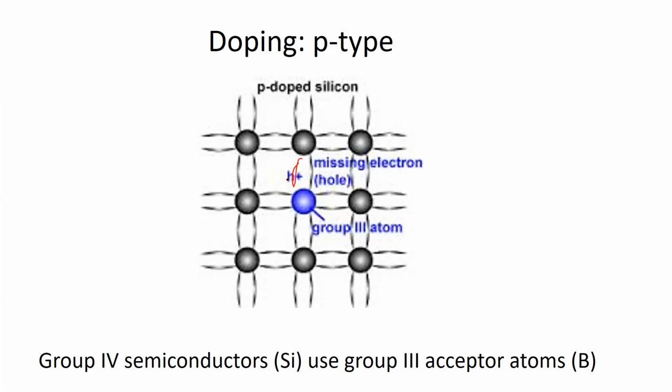They've got this extra electron, and so the boron atom becomes a negative ion. And these negative boron ions are located in the p-type material and form part of the crystal structure. They're not mobile. Because the boron atoms are generating holes by effectively accepting electrons from the silicon, we call them acceptor atoms, and the number of acceptor atoms introduced is called Na.